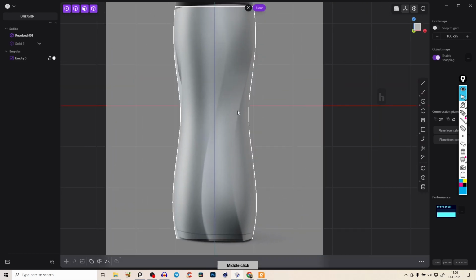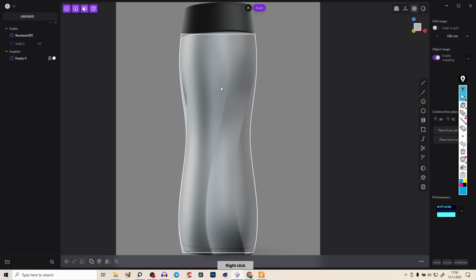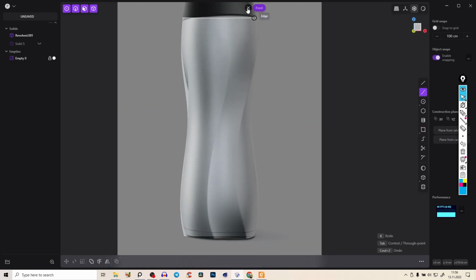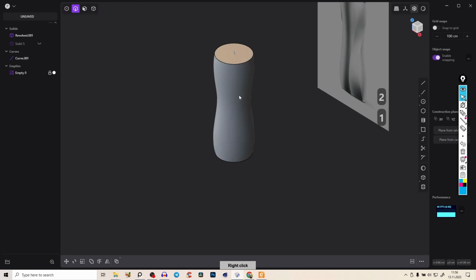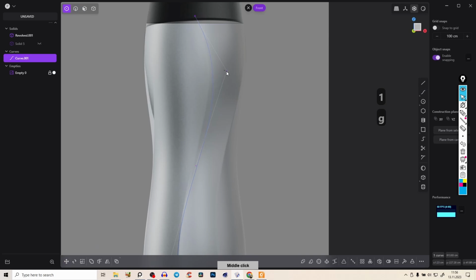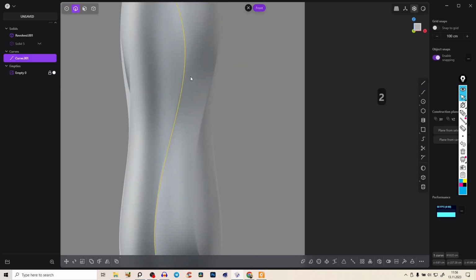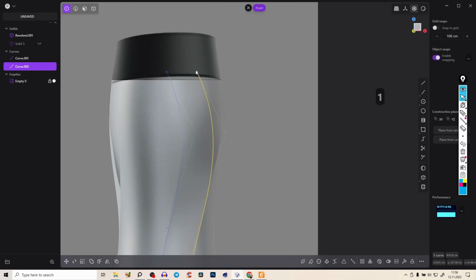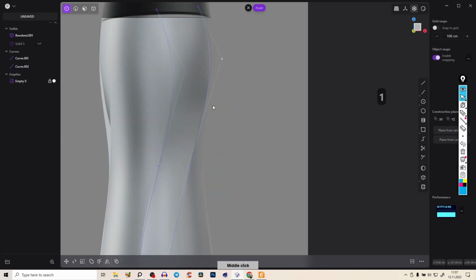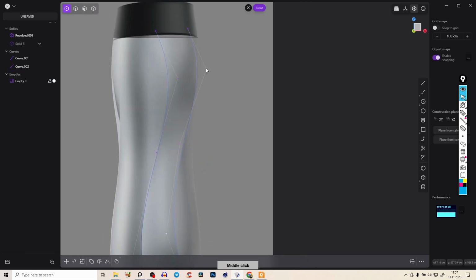And let's basically start here with this cool shape. So again, because we have a reference, we can just use it. And again, just create a spline curve and create here a nice curve with a few points. And again, just adjust. So if you don't see the curve very good, press G, bring it here to the front. Because now if you press 1, you just see those purple points a little bit better and just adjust them. So yeah, that looks great. And select this curve, Shift D to duplicate and just bring it over and adjust it again here where you have it on the sketch. So yeah, here for the tutorial, that should work.